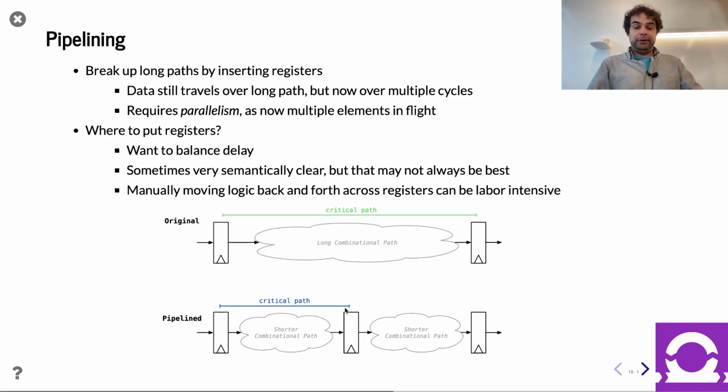If I don't have 2 units outstanding, I do unit 1 part A, unit 1 part B, unit 2 part A, unit 2 part B. That's not going to be any better, right? You'll have twice the frequency, but half the throughput, so it's going to be the same overall throughput. So the good news is for a lot of arbitrary designs, it actually is pretty easy to pipeline.